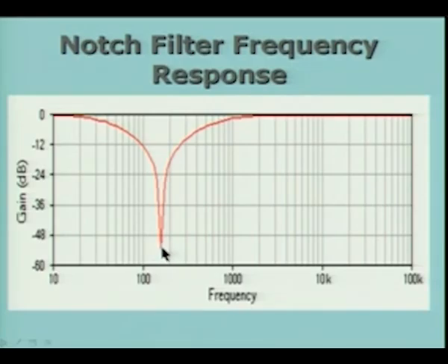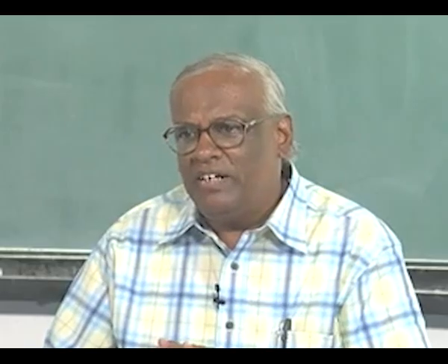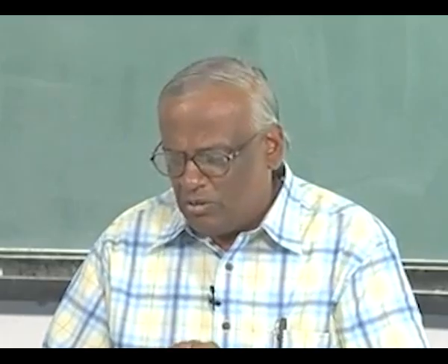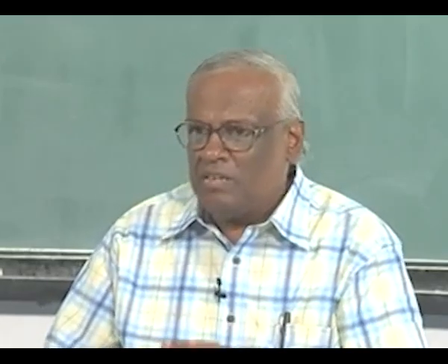If the noise is particularly localized at this frequency, you can have a notch filter designed with this as the frequency at which the notch is going to occur, so that you remove that particular unwanted signal and it will pass the other signals without any attenuation. And therefore, this is one way of doing it. So, signal conditioning means removing unwanted noise or unwanted frequency components, passing only what is required, and maybe amplifying it to the desired extent, and so on. So, these are some of the issues.